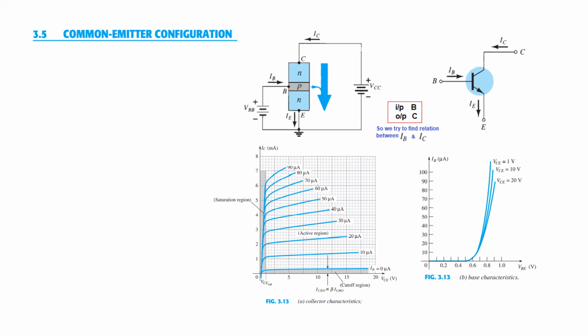The other curve is called the collector characteristics curve, which is again between VCE and IC, as we saw in the previous example also, and for different values of IB. Now as we keep on increasing IB, this graph moves up, but generally this graph has a very low slope. And we'll study the details of the active region in the next video. One important point which we'll be discussing here is this area from 0 up to this, due to the ICEO or ICBO. This is the collector to emitter leakage current in the cutoff region, when IB is 0. So this we will be using.